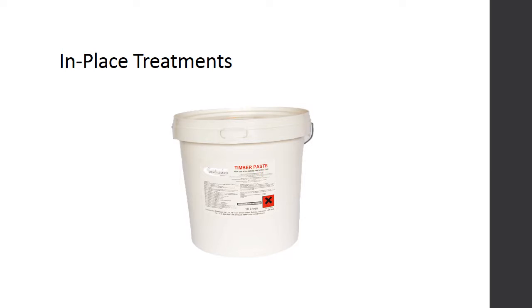Periodic inspections should seek to identify cracks, splits, and checks that result from normal seasoning, as well as areas of high moisture or exposed end grain and joint areas. These areas require periodic reapplication of a supplemental preservative.